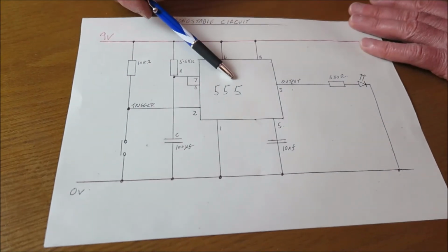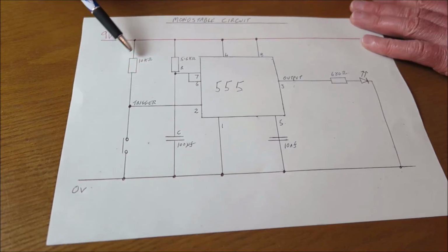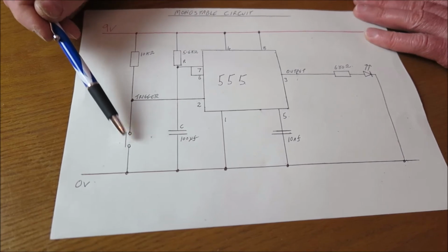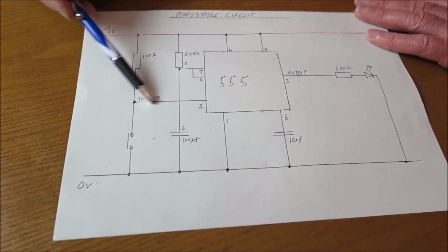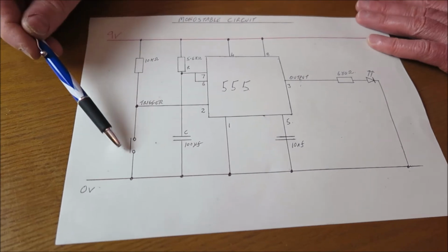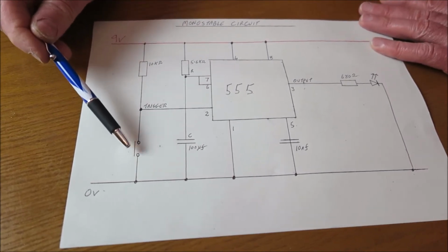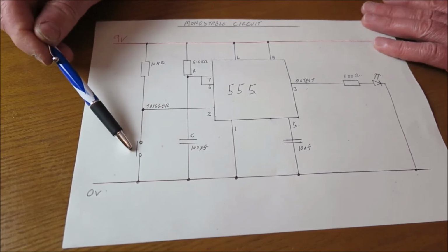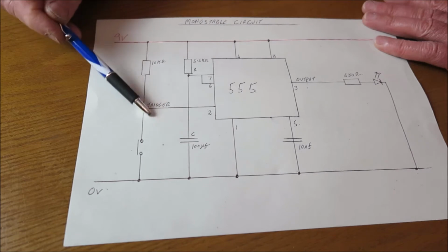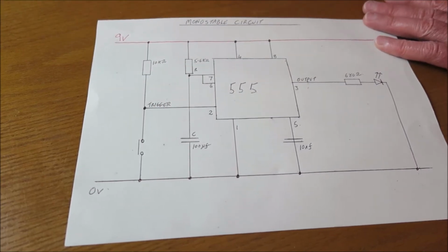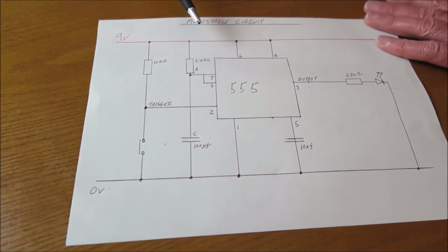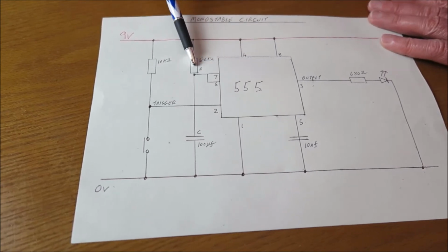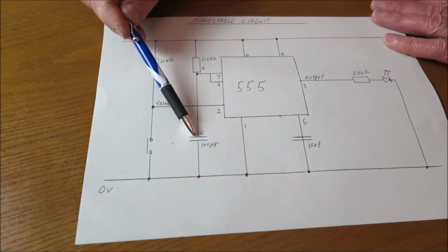This is the circuit. We can see our 555 timer here. Now what we have is this 10k resistor. Now this is a pull-up resistor. So when this switch is open, this is holding this at a higher voltage. It's not going to 0 volts. Because when the switch goes to 0 volts, if you remember when we were looking at the demonstration, we said that it was a falling edge device. So when we close that switch, this pulls this down to 0 volts, triggers the device to enter the monostable period. And then that monostable period is dictated by the value of that resistor and that capacitor there.